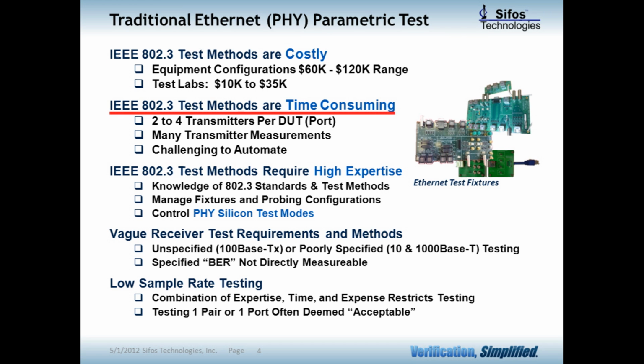Secondly, there is nothing fast or easy about these measurements. Measurements typically address one Ethernet transmission wire pair at a time. A 24-port gigabit Ethernet switch with an auto MDI feature presents 24 10 Base-T pairs, 48 100 Base-TX pairs, and 96 1000 Base-T pairs for testing. There is virtually nothing in common between these transmission technologies, so the full coverage of this 24-port switch consists of a series of measurements on 168 transmitting pairs.